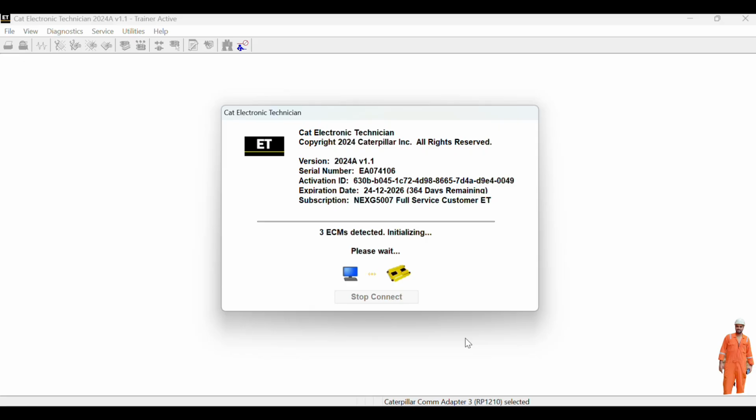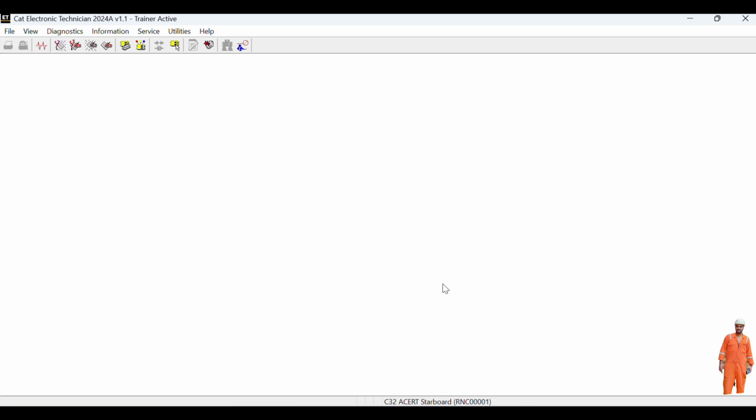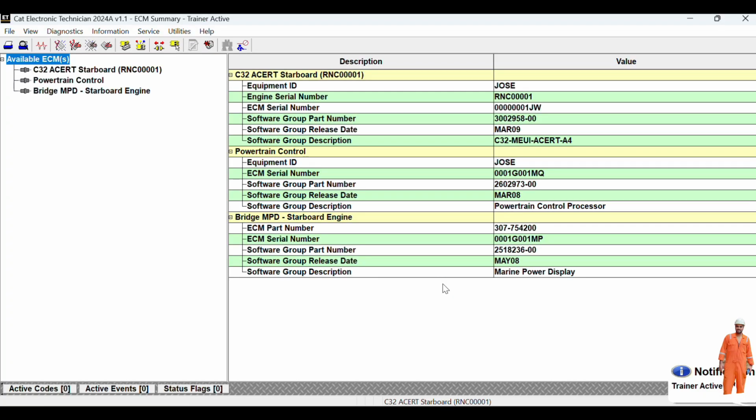technician. First one is to get the information of parameters, events, codes, diagnostic information or code generations, and engine configurations. Second one is to perform various tests, there are various diagnostic tests. I will show you the calibrations of various sensors as well as injectors, then flash programming of the ECM module if there is any upgrade or error, and configuration of the electronic control module which has been newly installed.